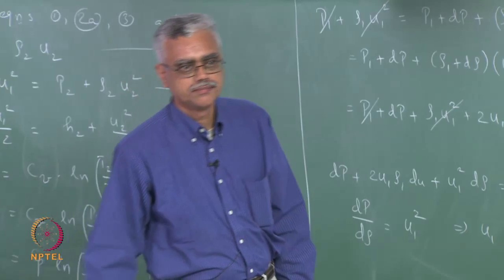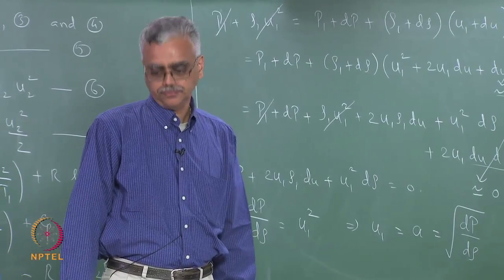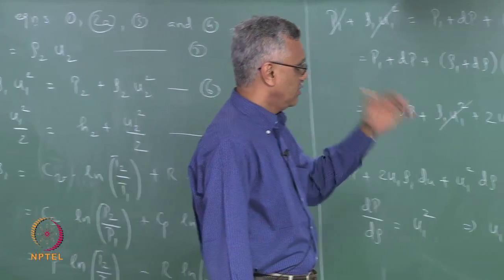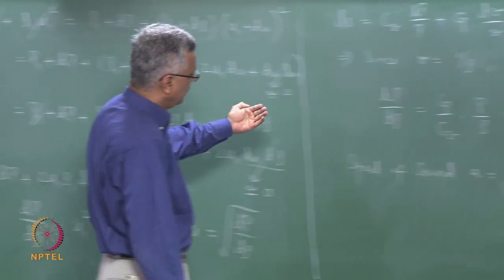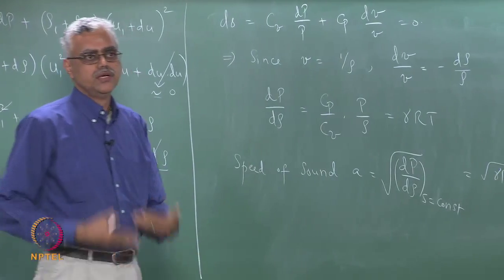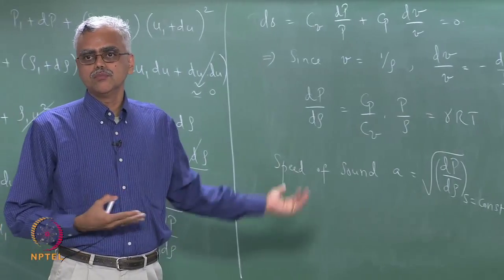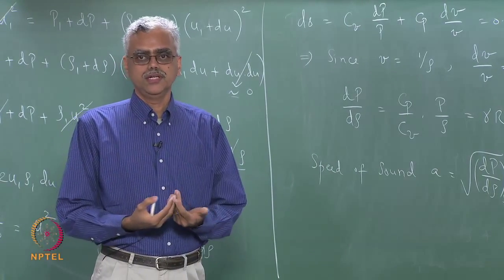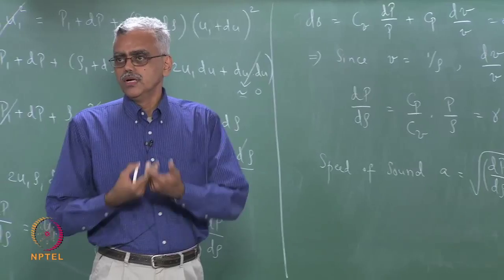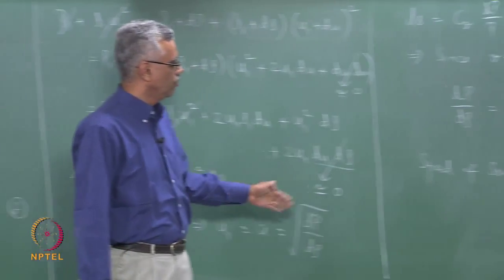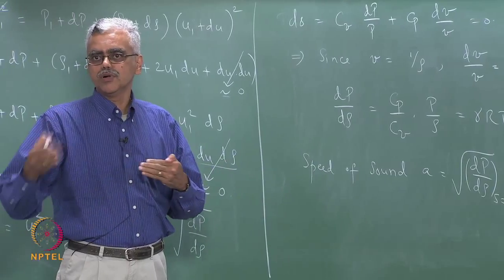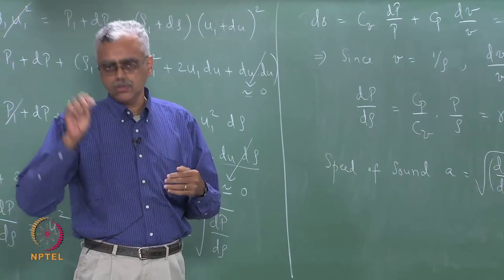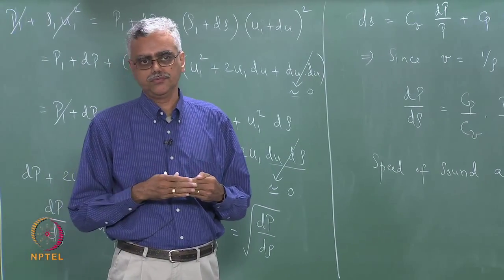Are there any questions? Okay. Now, you can see that the solution that any infinitesimal pressure disturbance must propagate with the speed of sound comes out of our governing equations naturally. That is one of the permitted solutions. And notice that because we are talking about a wave, this is a discontinuous solution. The changes in properties across the wave are discontinuous, although it is infinitesimal, it is still discontinuous.